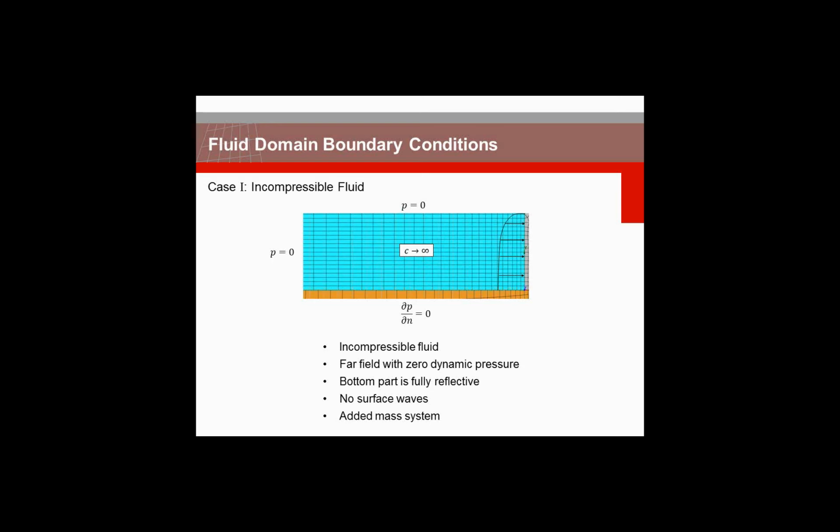You've worked previously with this kind of Westergaard approach. This is a kind of added mass system. This means that the whole influence of the fluid on the structure is reduced to an additional mass, right? And this is the case.